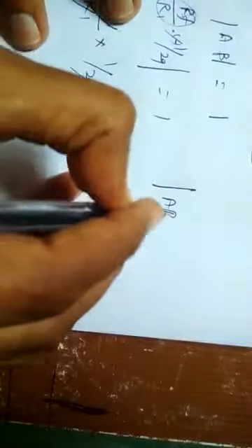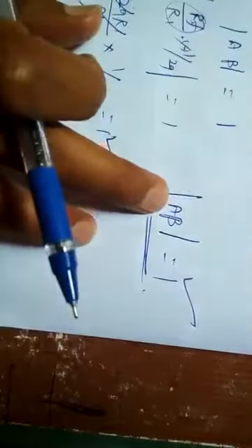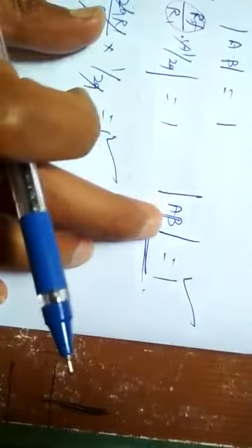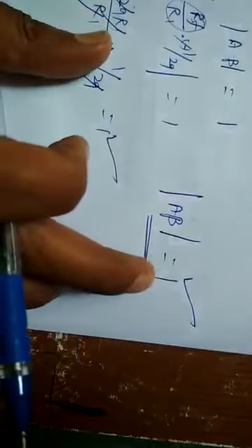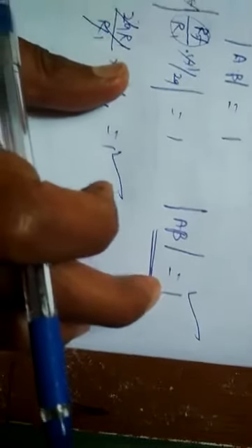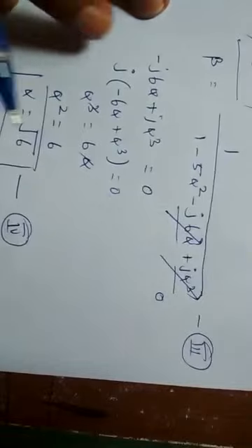So modulus of A beta equals 1. The absolute value of the product of the forward path and feedback path gain is proved as unity by considering only the value of RF equals 29 R1. This RF equal to 29 R1 has been proved by solving the expression for beta.